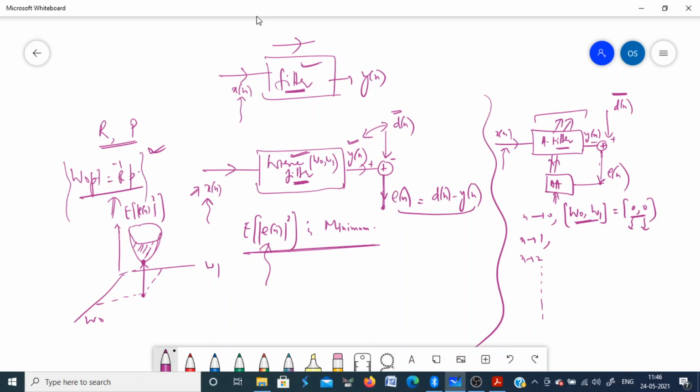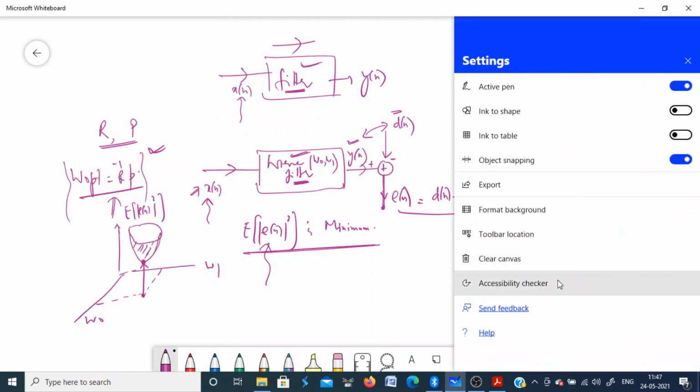Okay, so this filter is generally used for cancellation of noise when the signal and the noise overlap. We also use this structure for removal of 50 Hz interference and also for cancellation of maternal ECG from abdominal ECG to get your fetal ECG. Okay, so we may come to this again at a later stage. But this is how adaptive filters work.